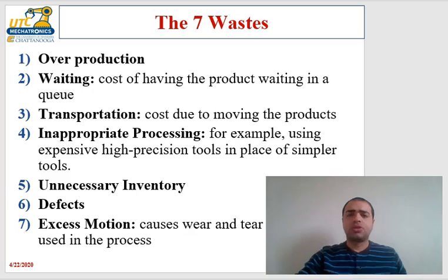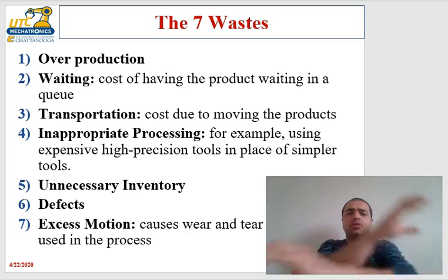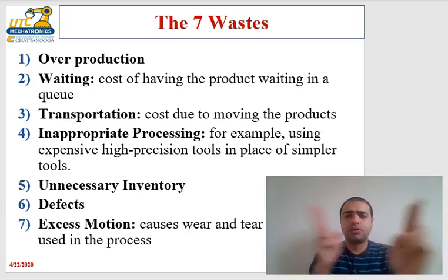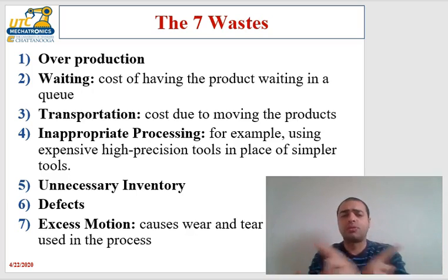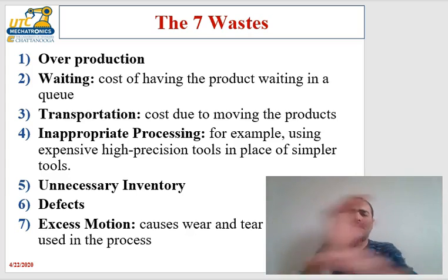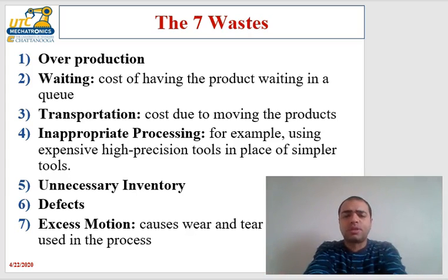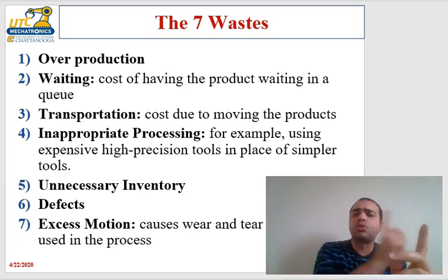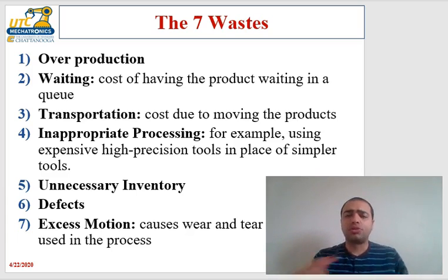The idea was that you should never cross hands, or if there are 2 operators, they should never cross, to pick up something from here. If you ever cross your hands, that means you need to get whatever is here there, and whatever is there here. So crossing hands basically means you are wasting. There's transportation waste. An operator crossing the other operator means there's a transportation waste. So the idea is to reduce that.